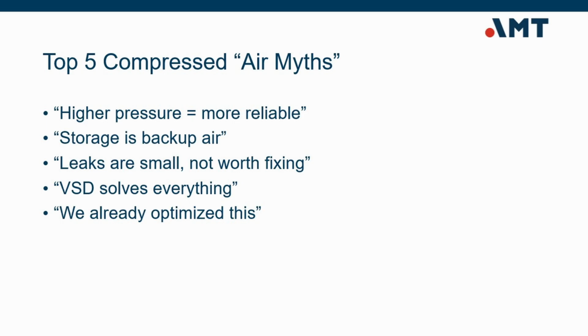Myth number 4. A VSD solves everything. Variable speed drives are powerful tools, but they're not magic. If the compressor is oversized, if pressure is too high, or if leaks are excessive, energy waste will still occur. Technology must be paired with proper system design and control strategy.